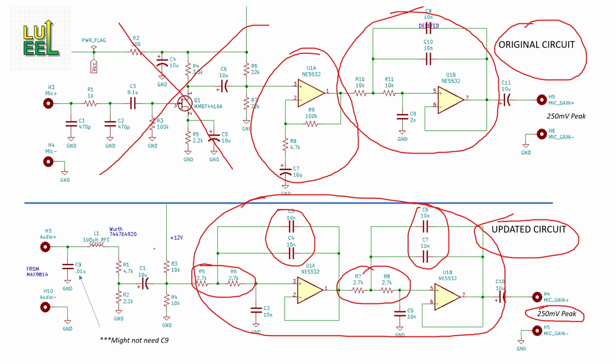DC offset? I'm going to need to knock that down, and the easiest way to do that is with this resistor divider here, R1 and R2. Cap C1 will block the Max's DC offset and set a low frequency cutoff. R3 and R4 set a 6 volt DC bias for the op amp chain so I can use a single-sided power supply. And L1 is a 100 microhenry RF choke. I'm adding that to help block any stray RF that might try to enter the circuit.